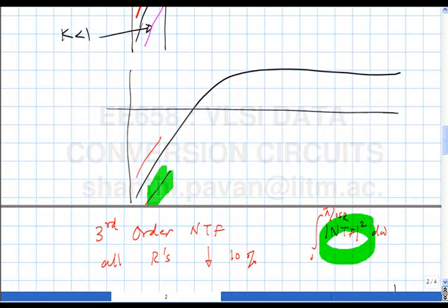So physically, what can you see in the waveform? Ideally you were expecting a nice sine wave with some shaped noise. If the out-of-band gain becomes worse, the sine wave will still be there, but the fuzz on top of it will increase.